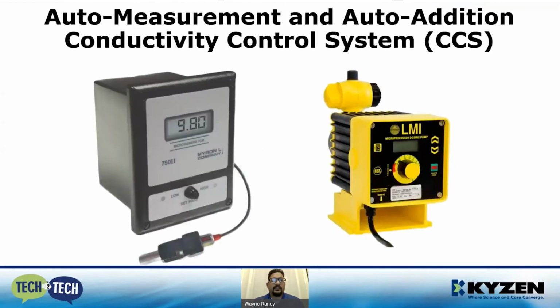This system uses a conductivity meter to measure the conductivity of the wash bath, and a metering pump to make the necessary additions of chemistry to get the concentration to the set point value. When concentration, as read by this conductivity meter and probe, goes lower than the set point, the CCS will automatically add chemistry by way of the metering pump to the wash tank until the conductivity reaches the target value.